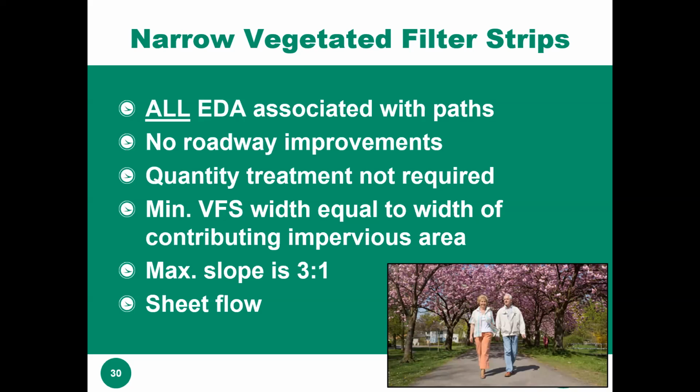It's important to know where you are. I think in the City of Columbus, it's 2,000 square feet of new impervious area that drives the need for detention, like restricting the 100-year post-development peak flow rate to the 10-year pre-development peak flow rate. Well, 2,000 square feet is less than a block of sidewalk. So you can get into some complicated post-construction BMPs that really drive up the cost when maybe the grass right next to the sidewalk is plenty.